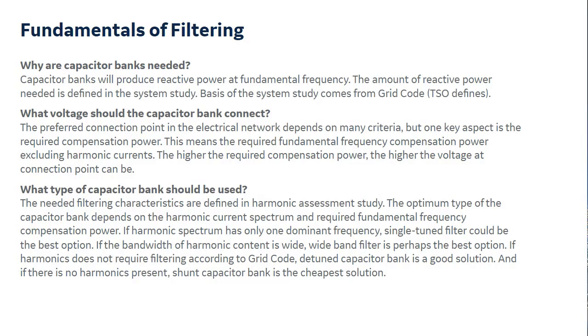And then, at what voltage should the capacitor bank be connected? The preferred voltage point depends on many criteria, but there are a few key aspects. The compensation power is one, and then the connection voltage is another one. Sorry, the fundamental frequency compensation power, and then the harmonic content.